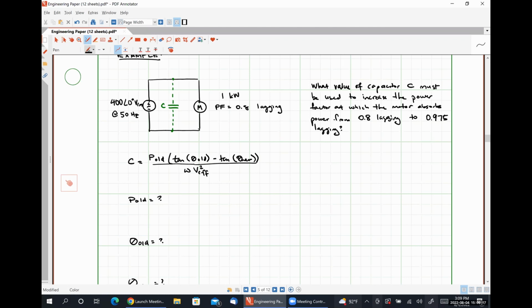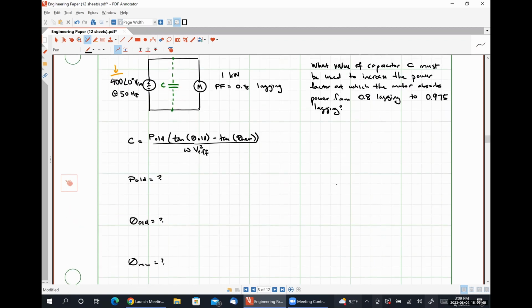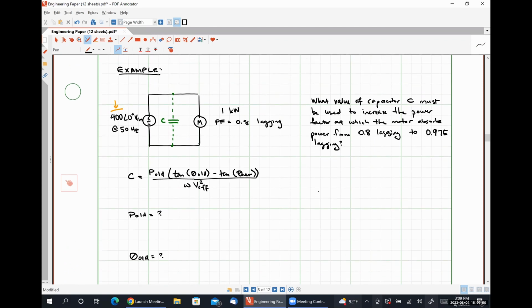Okay. So effectively, we're just looking for this thing right here. Whatever the magnitude of the voltage drop across the capacitor is the V effective that we're looking for. So I'm going to come down here and I'm just going to call this 400 volts RMS by inspection. We didn't need to do any work for it whatsoever.